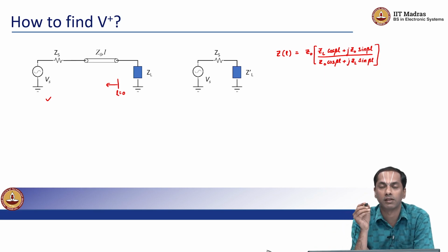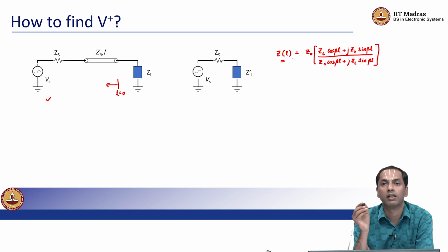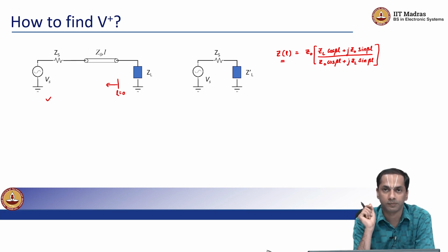So this is to say that the voltages and currents and their behaviors on this transmission line are not constant, right. The amplitudes of their oscillations and their phases change as we go along this transmission line, and this can be captured as saying that mathematically it is like truncating the transmission line at a different position L not equal 0, and then replacing the ZL with the Z as a function of L that we have here at that new location, right.